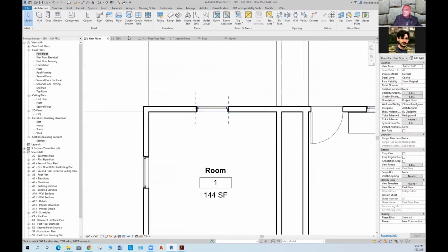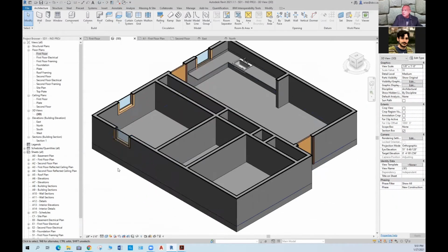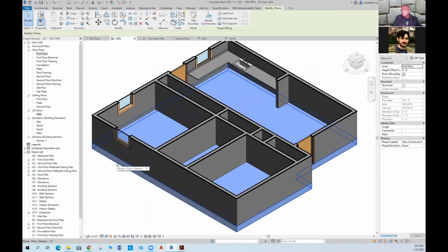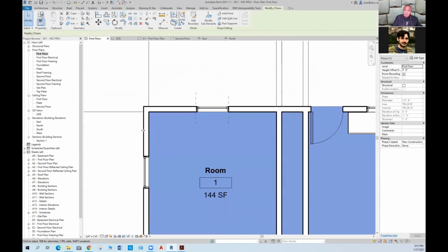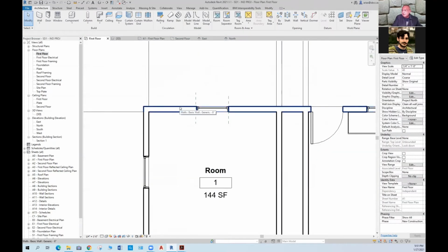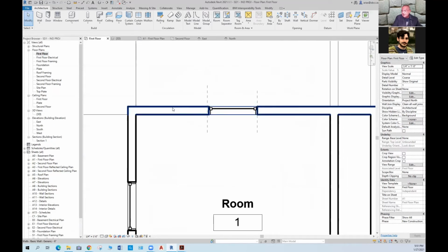Or in other words, we have the possibility of selecting any object that is perpendicular to that cursor. For example, let me go back to 3D. We do have a floor that is aligned to the walls. So if I go back to this view, I could select the floor from here. Right now I can't because it says there that I'm selecting the wall. But if I leave my cursor there and then press the tab key, you will see that at the bottom left corner where I'm pointing to, the program is going to indicate what object you can select.